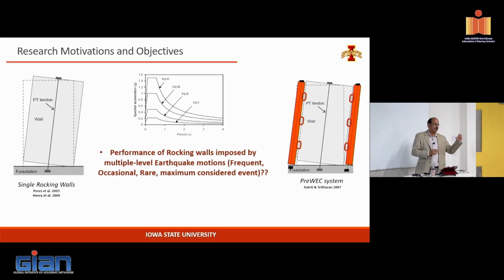So design level means it represents an earthquake every 500 years, let's say, whereas the EQ4 is, at least in the US, a once every 2,500 year event. Is that the same here, or do you only design? Simply say 2005, 2007. Okay. Yeah, somewhere in that number, right? So since we are testing it, we wanted to make sure that it can not only, so we design it for this, but we wanted to make sure it also can survive that particular maximum considered. At least we wanted to know, can it survive a maximum considered event?